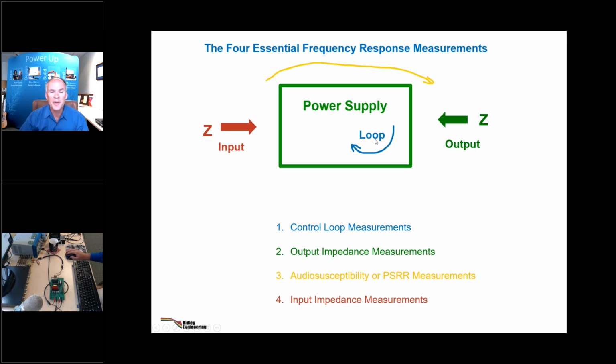Noise reason is obvious. And then the loop, of course, is what is controlling things like input impedance and output impedance. Input impedance is of particular interest because every converter that you build, assuming it's got some efficiency, will have a negative input impedance. And you all know this, when you're sitting on the bench, you dial up your input power supply, and then when it hits regulation, the current starts to drop. So that's a negative resistor, and that negative resistor likes to talk to anything ahead of it and excite it and make oscillations.